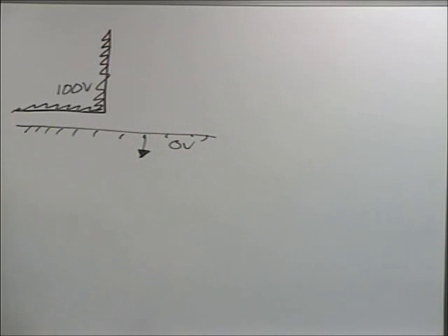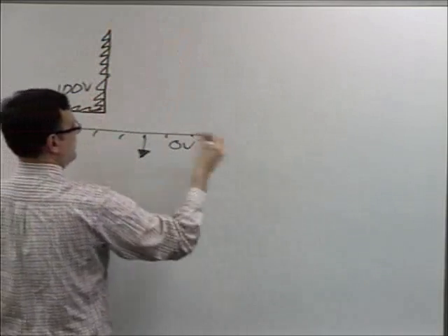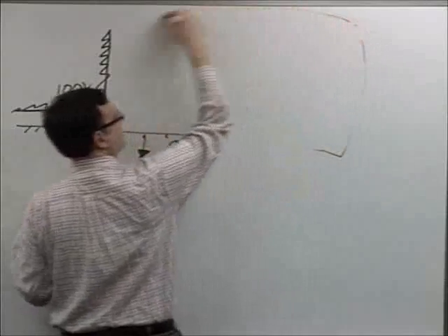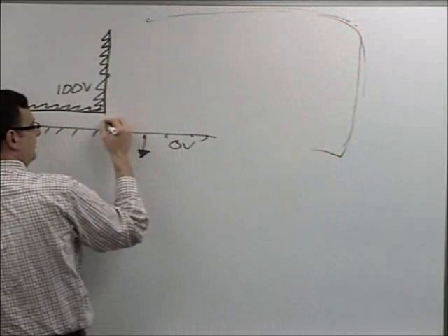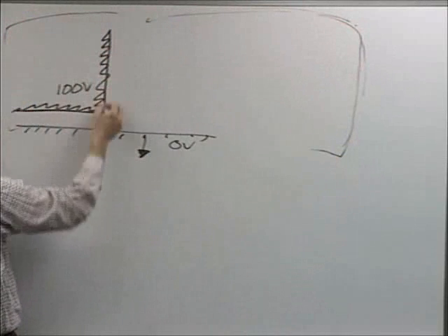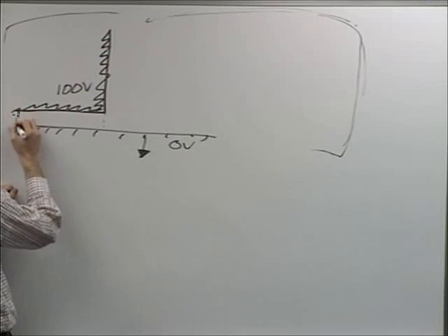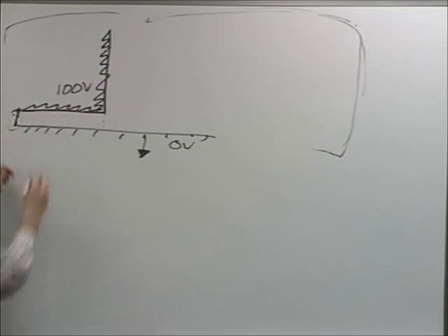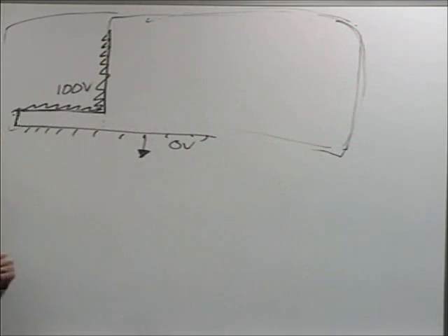Well, this is something that we could discretize and come up with a boundary value problem. We'd make the space really big, set this out to 0 on the edges here, maybe interpolate a little, either enlarge this so that it includes the corner, and then interpolate from 100 volts to 0 volts in a steady manner down there. And this would effectively be our boundary. And then we could use that technique where you just average the nodes around and iterate the solution to something accurate.